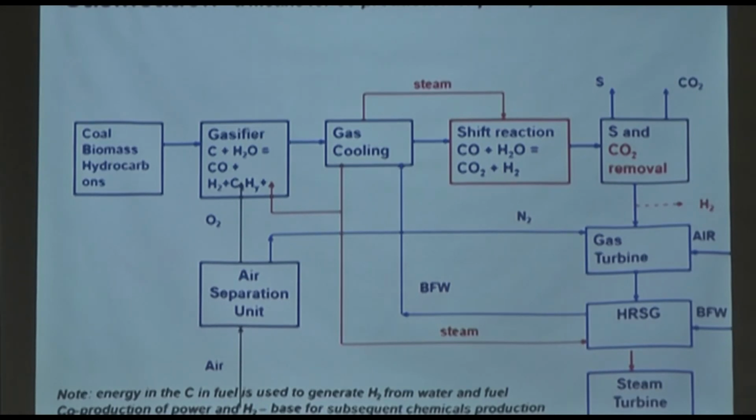No, before the gas turbine. So, if you want, that is why I have put the line as a dotted line, optional. Correct. If your focus is hydrogen production, for example, the project that I am advising on now in Victoria, hydrogen production is the focus, gas turbine is not. So this part does not exist, it finishes there. That is the flexibility of the gasification process, that you can literally get whatever you want, not just power, but chemicals also.